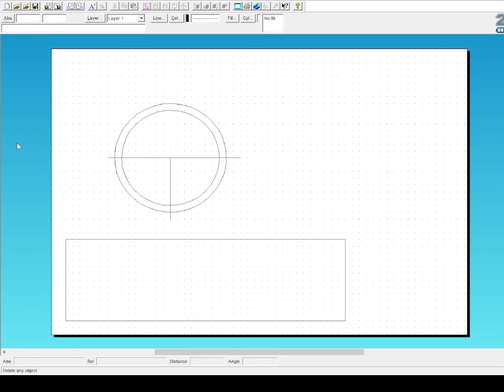So I'm going to delete away what I don't need. I'm going to use part delete, which is left mouse button held down over the delete any, and I'm going to part delete those bits of this circle away. Okay, right, good, so far so good.